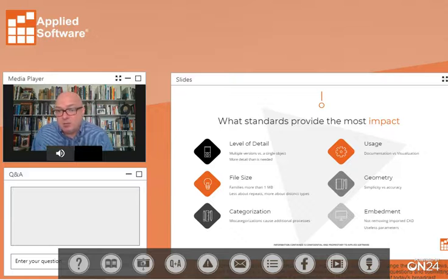But I also think, too, something that not everybody thinks about, and is the case to me where a lot of problems end up, is embedment. When I say embedment, things embedded into the family that are not useful or are no longer useful, right? Because I think it's okay to be building content and then bring in templates or 2D diagrams of things from outside. A very common one is I'm going to rebuild something from, say, an AutoCAD file. I'm going to load that AutoCAD file in, I'm going to trace around it, and then you end up maybe turning it off instead of deleting it, getting rid of it and clearing it up. And so it ends up being an artifact inside that family. And if that family's then copied around everywhere, suddenly now that is propagated, right? And that will kill your performance.